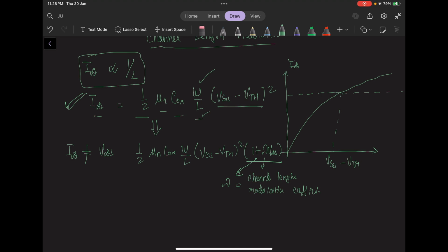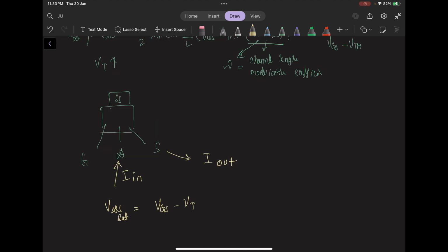So in an ideal MOSFET, drain current will remain unaffected by VDS. However, this only happens after the threshold voltage is met. After that point, in the saturation region, drain current should remain unaffected by VDS. However, due to channel length modulation, drain current actually slightly increases with VDS, which is very similar to what we had learned in the earlier FET.